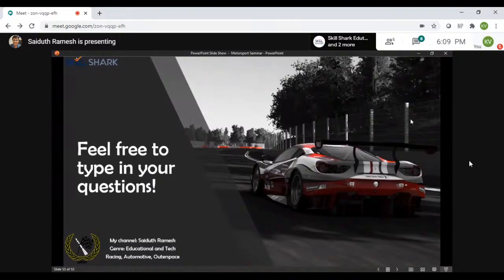So racing slick tires have a really good contact patch. They have maximum contact patch, which means, in your road tires you basically have grooves in it, right? That's called tread. The reason we have that is because it's an all-purpose weather tire. If you go on a dusty surface, or even normal roads, and especially in India, roads are a bit more dusty. It's a tropical area, so there's a lot more dust. So it really makes no sense to have a tire that is completely flat, and most parts of the world have a lot of dust. That's why we have that.